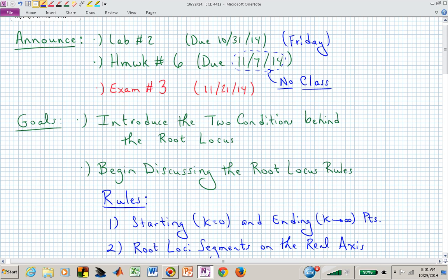All of that is based on this assumption that your model from lab number 1 is correct, but you might see, based on the performance or response that you're getting after controlling your system, that maybe it's not quite what you thought it was initially. But you also have to realize that the system you are producing with your model is an ideal two-pole linear system, and we have some nonlinear behavior or some friction in there that may not be modeled by our plant.